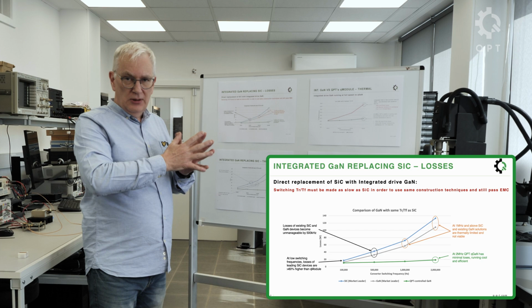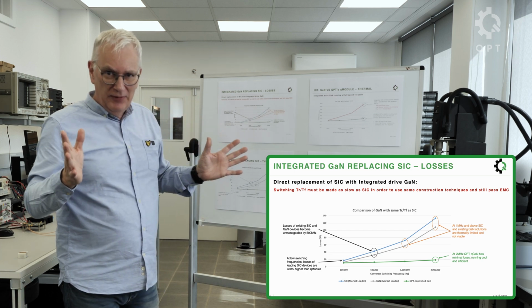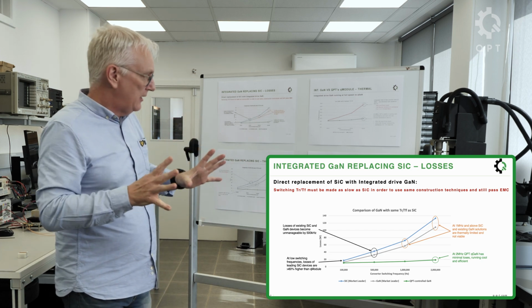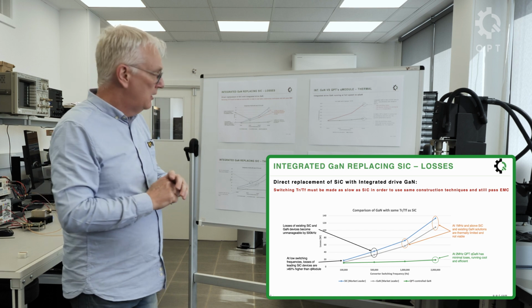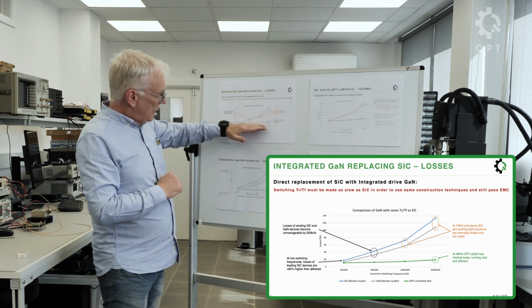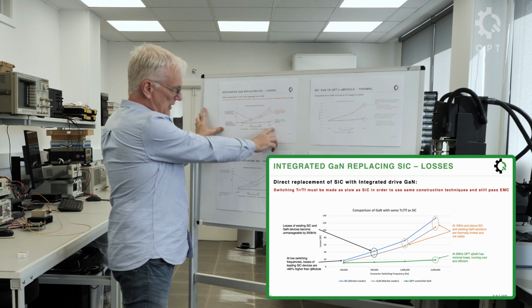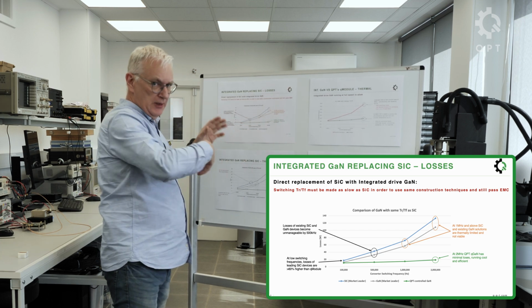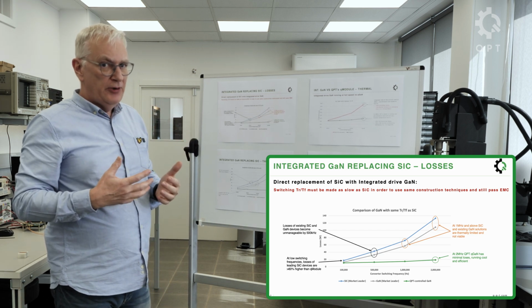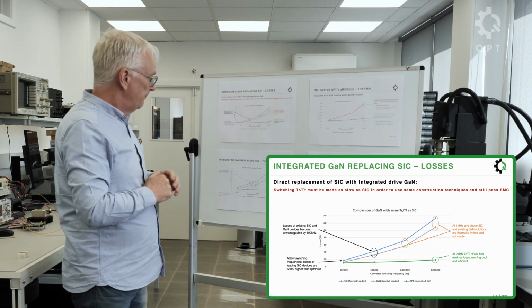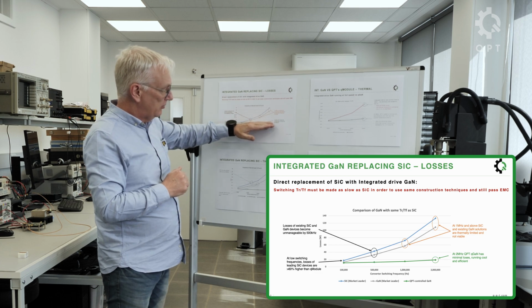But with our solution, basically the heat just comes straight out. We've got the lowest thermal resistance of any component on the market. So we're basically flatlined. So as the switching frequency of the converter goes up, our power dissipation doesn't really go up very much. It's almost flatlined. So that means that our losses don't go up.